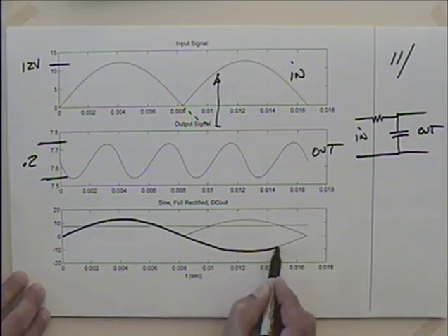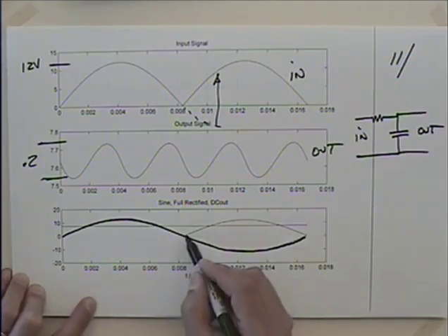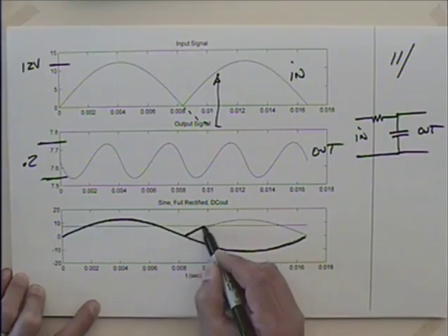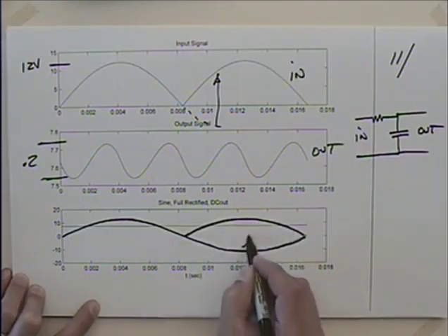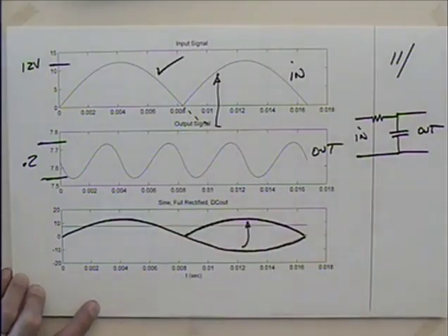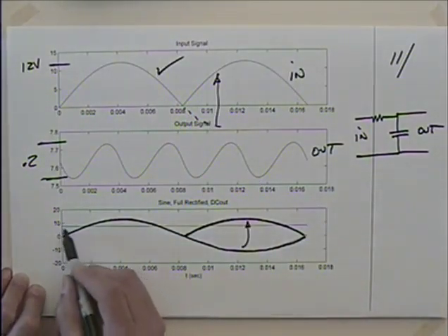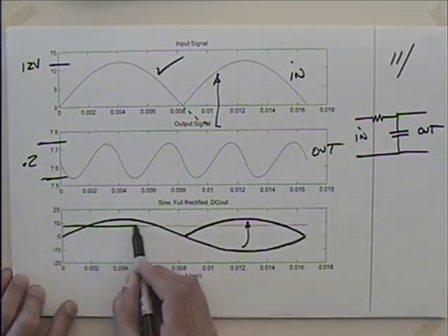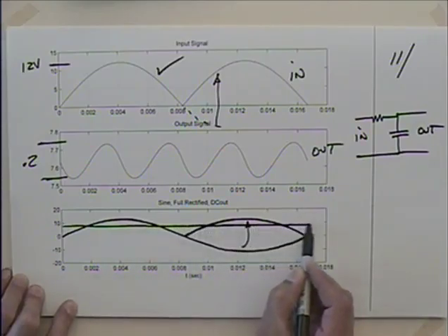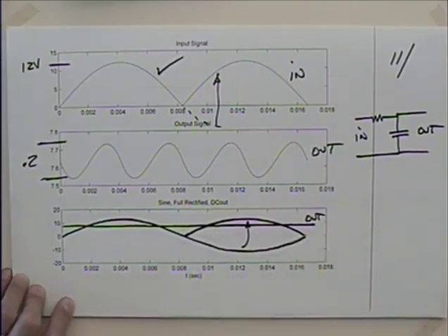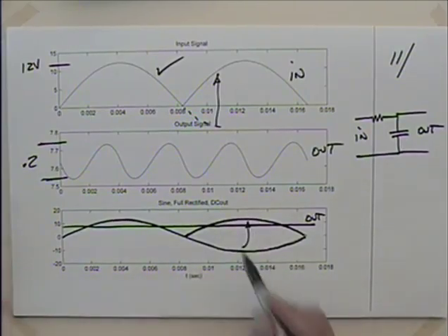that's the sine wave that's coming out of the transformer. Okay. And then I use the 4 diodes there, the diode bridge, the rectifier, and I flip that one up. That's what we started with right there. And then this is our output, which is pretty good. I mean, when you look at it in the same scale, these go away, right? You get something that's pretty smooth. So that wouldn't be a bad power supply for us.